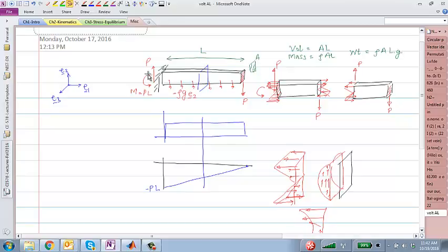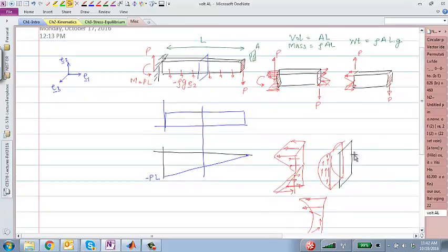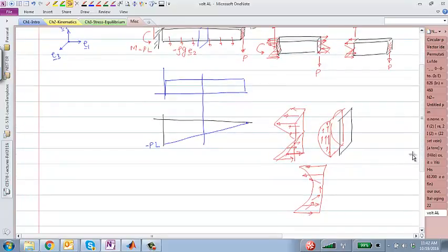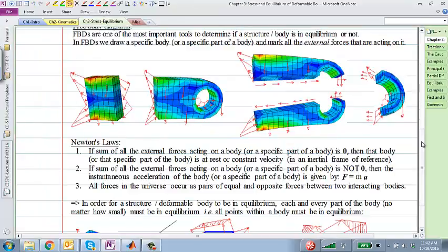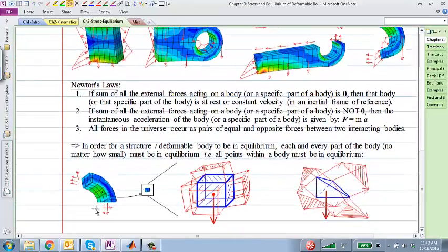Either it's a distributed force per unit area or per volume. So these P and M L, or these shear force and bending moments, are resultant forces and moments which are obtained by doing a vector sum and integrating over the area of the cross section of these distributed forces. So these are distributed forces which we are really going to focus on. All right, so back to this.